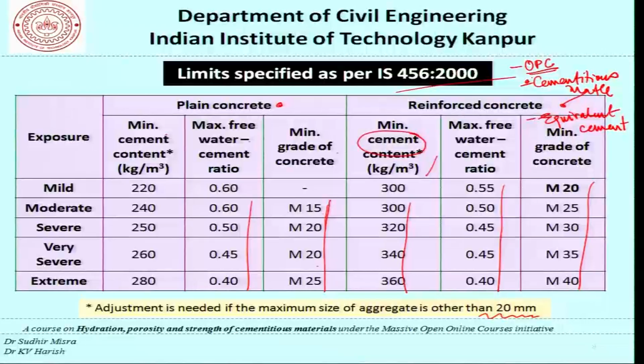part of this cementitious material, depending upon its efficiency, is taken into account. So, this whole idea of specifying a water cement ratio or a water to cementitious material ratio is something which we need to keep in mind, and it sometimes becomes one of the issues where there is no agreement between, let us say, the contractors and the clients or the owners and so on.